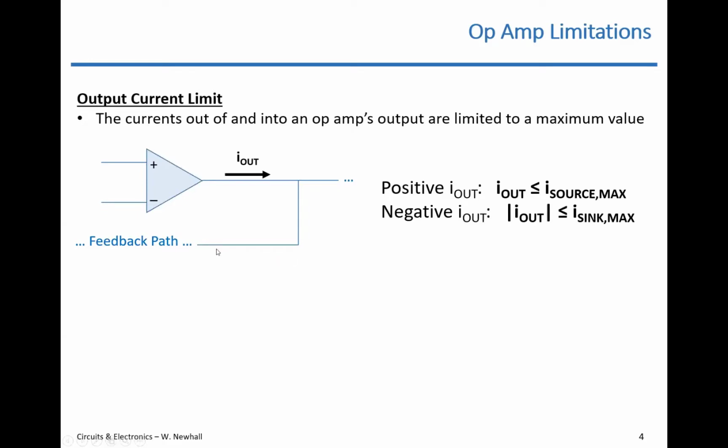That's important when you consider, and I didn't bring this up last time because we hadn't talked about this, but the inverting and non-inverting amplifiers, their gains are dependent on the ratio of resistors, not the absolute values of the resistors. Well, here, this is a consideration.